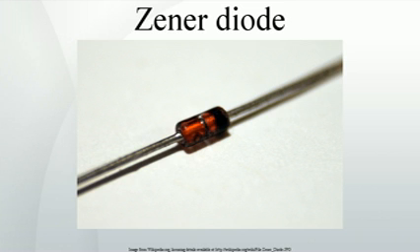Modern manufacturing techniques have produced devices with voltages lower than 5.6 V with negligible temperature coefficients, but as higher voltage devices are encountered, the temperature coefficient rises dramatically. A 75 V diode has 10 times the coefficient of a 12 V diode. Zener and avalanche diodes, regardless of breakdown voltage, are usually marketed under the umbrella term of Zener diode.